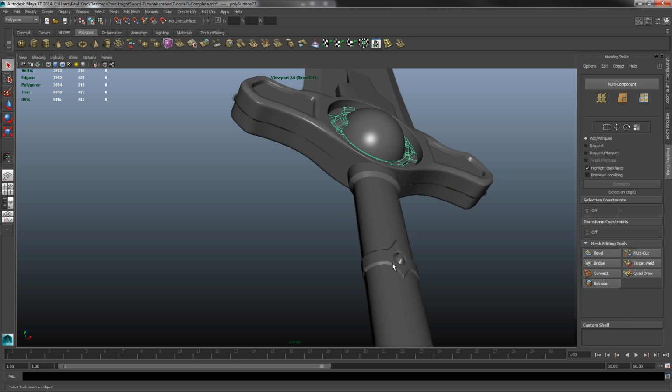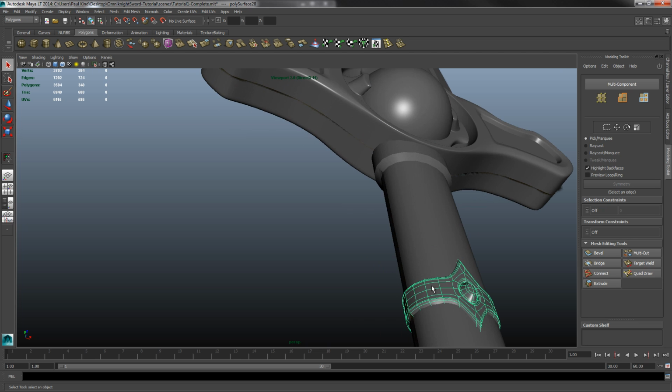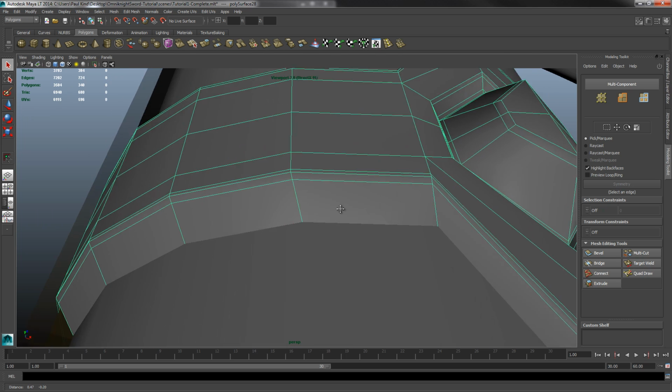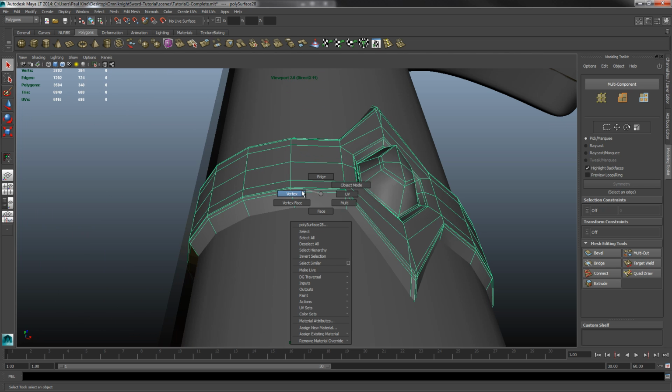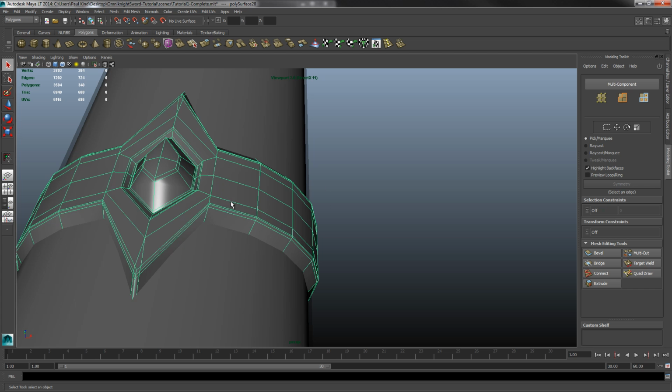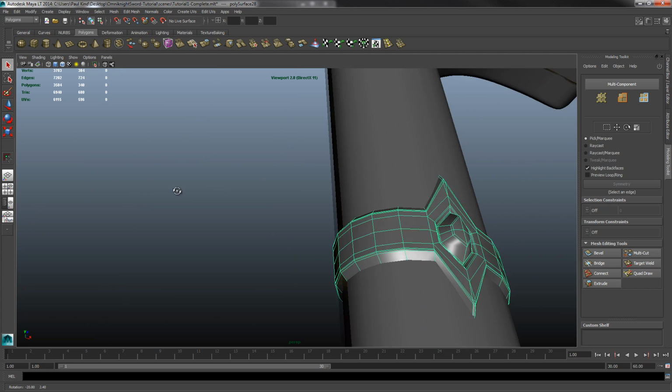I think I put a control loop in here just to sharpen up this edge, right there. See it? That lower one. This guy right here. Let me hit 1. So all I did was I added this one singular control loop, right? Edge right there. And I put it on the other side too, on the top, so it's right there. So that just sharpened that up and made it a little cleaner. But yeah, you can add control loops as you need.